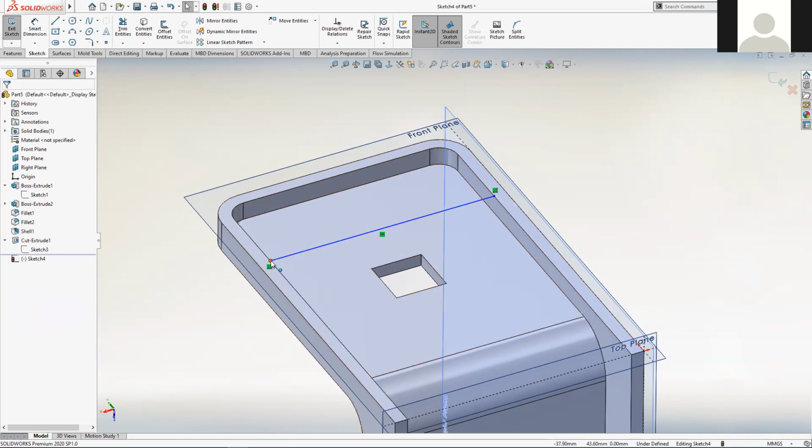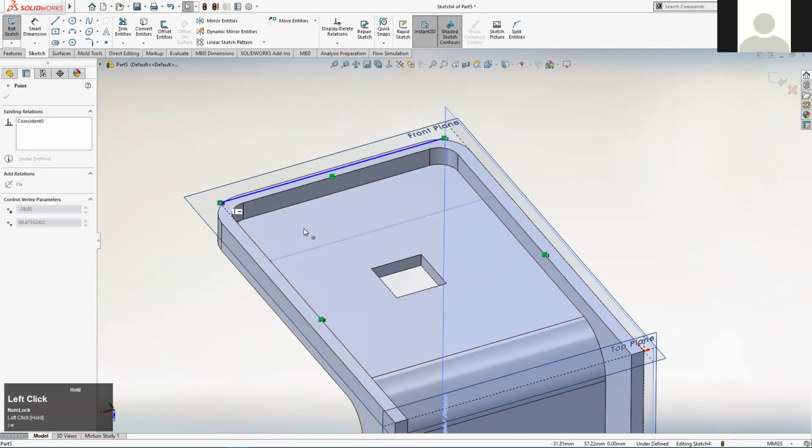And then I might investigate how is this line free to move. So you can see if I just click and drag on one of the ends, it is attached to that edge. And again, by that edge, I mean the system regards that edge now, because it's perfectly straight, as extending off into infinity. So you can see I can drag beyond where the edge is. In that sense, the edge just goes on and on and on. But I can't drag this point off the actual edge itself. It's always coincident with it. And same with the other end. I can't get that point to come away from the edge, but it will extend off into infinity like that.